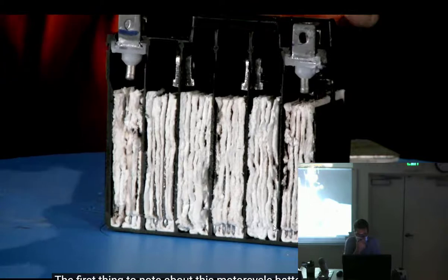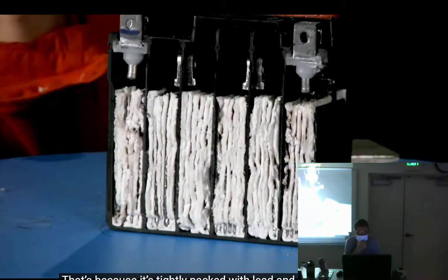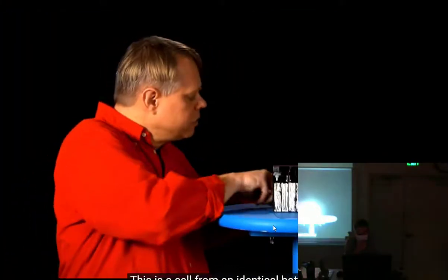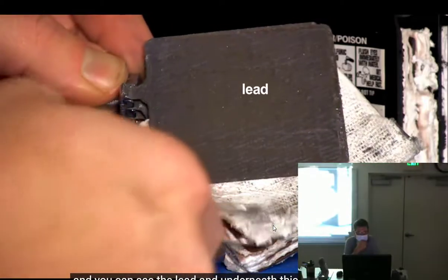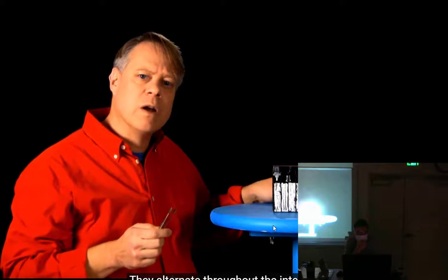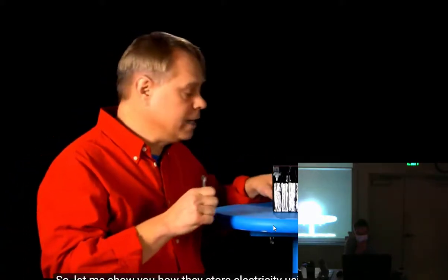The first thing to note about this motorcycle battery is that it's heavy. That's because it's tightly packed with lead and lead oxide sheets, both of which are very dense. This is a cell from an identical battery, and you can see the lead, and underneath this, the lead oxide. They alternate throughout the interior. So let me show you how they store electricity using just 2 plates.